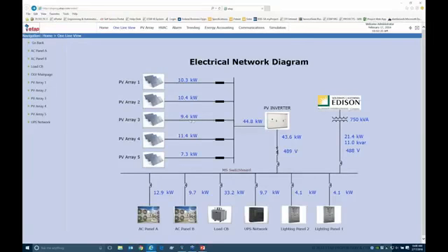So you can see from each section, from each combiner, we are seeing about 9 to 10 kilowatts. And obviously the last group, as I'd mentioned, was only 7 strings, so you'll see about 7 kilowatts or so coming from that group. Going into the inverter, here's the inverter output, and here's the power that we're buying from the utility.